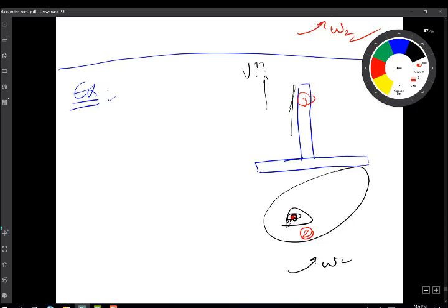Okay, so now let's count our points one more time. So I'm going to say, okay, this here is point number 1, 2. That's correct. And of course, the follower slides up and down. So perpendicular to the direction of sliding is 1, 3, goes to infinity.